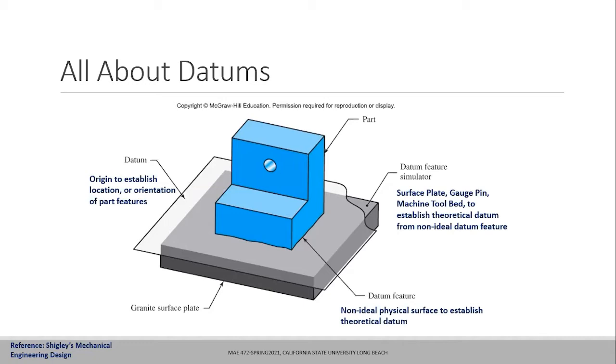What does datum basically mean? Plane or spot where you use it for reference. Mm-hmm. Yeah, that's a perfect definition of a datum. It's basically a plane or some slot or some origin from where the measurements will originate.